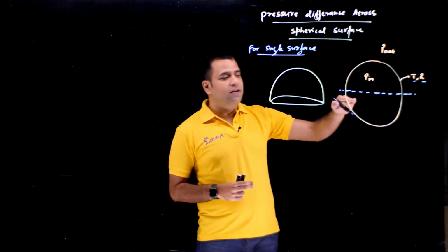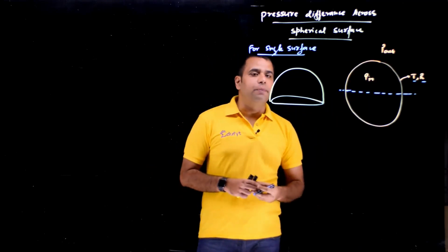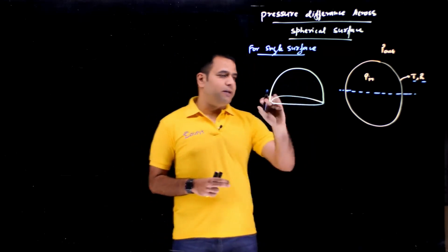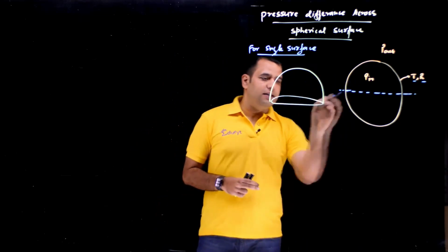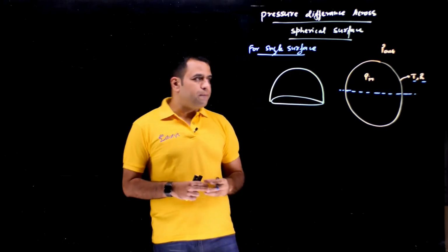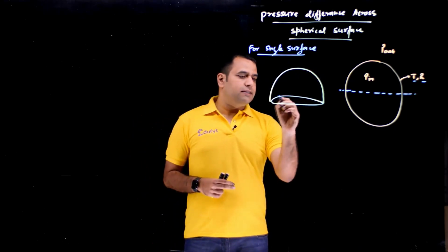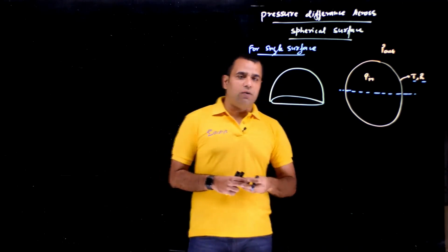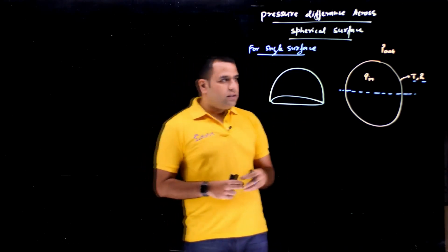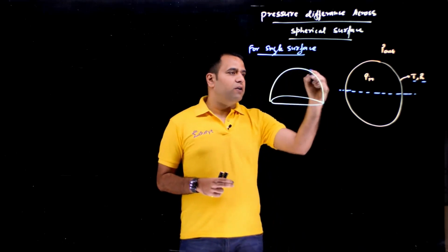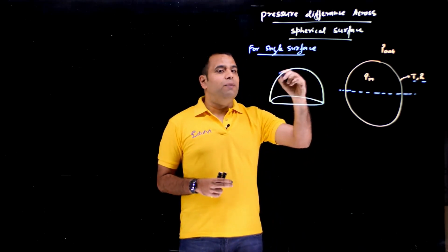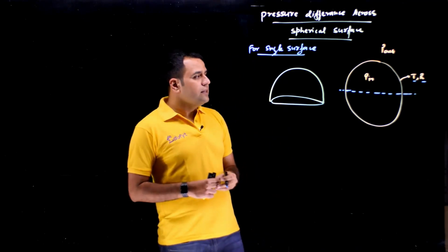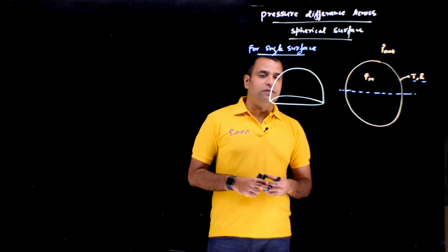Okay. So, that's what we will do. We'll cut it in half and we'll calculate these three forces separately and the net force we will make 0. Okay. So, this is my half sphere. I've cut this sphere in half. This is my half sphere, and in this sphere if you see, this is the periphery of the sphere. And since this is the periphery, first I'll calculate the surface force. This surface force acts everywhere onto the surface and everywhere it will be 0 except at the periphery, that we learned. At the periphery, this surface force will be non-zero.